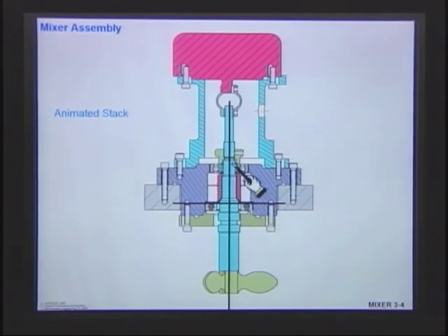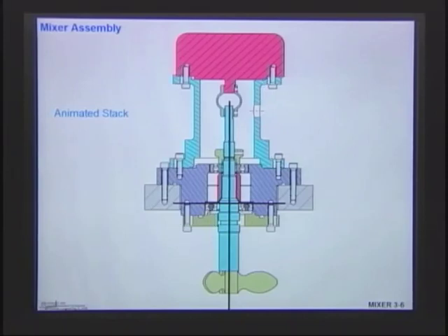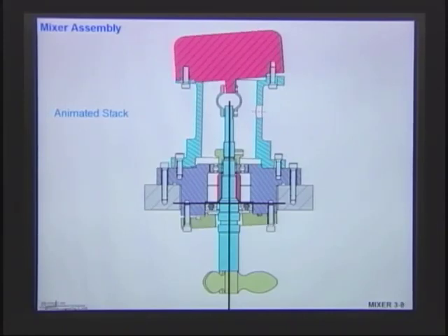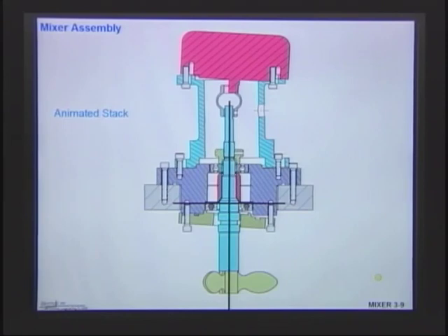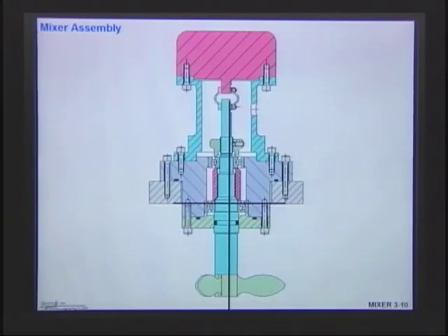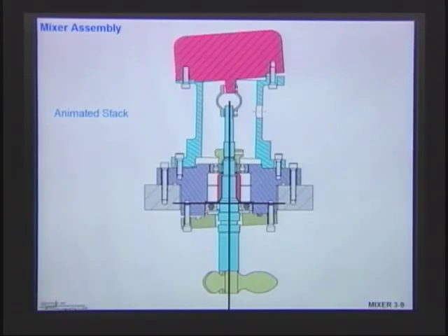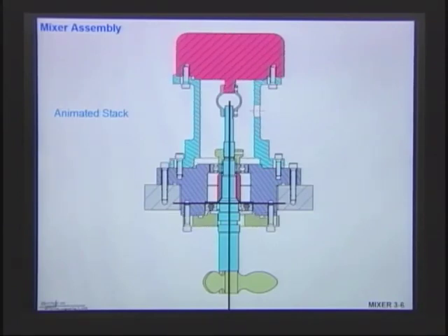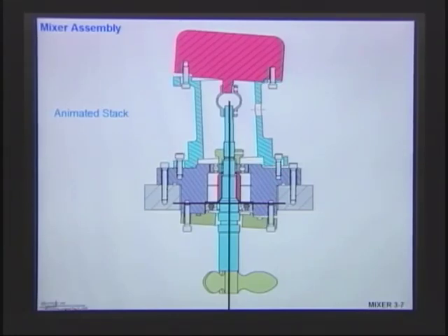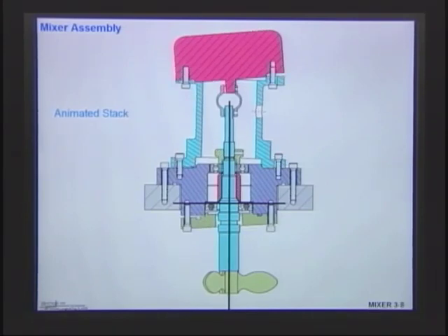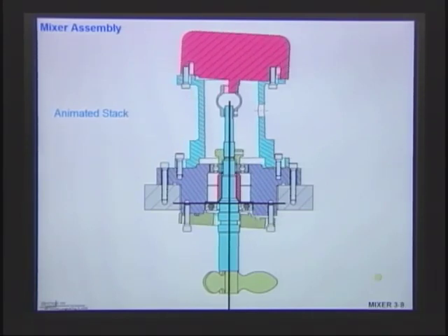So what I did is I drew a black line in here on the datum reference frame. Now this is the way you want to kind of think about it, right? As things moving. The shaft is always there in the center, and all the other components are moving about that, right? So that's the way you want to imagine that thing. See how everything is moving? I say, oh my gosh. But that's really what's happening. It's just smaller tolerances, right, as they're moving around. So we're going to do a tolerance stack based on that, and then see where everything can be. So that should have been our thought process here.